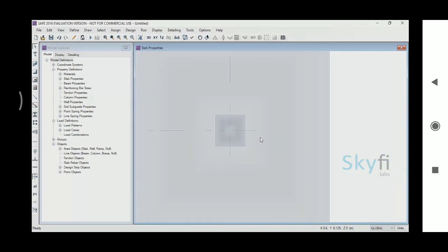If you zoom in, you can notice that the footing and stiff options are displayed one on top of the other. The software has automatically assigned the stiff property to the column on top of the footing when you assign the footing property. This is because you had used the single footing template. So when you assign the footing property to the slab below, the software automatically understood that the column above possesses the property of stiff, and hence assigns it automatically.